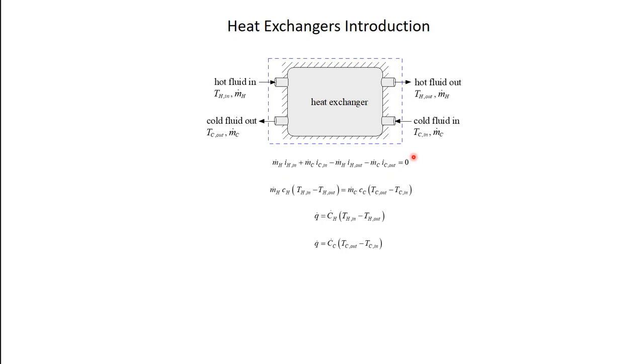If I want to go from this equation to the next equation, which is the one we typically use, I'm making another couple of assumptions, basically related to how enthalpy is behaving. I'm assuming that enthalpy can be written as specific heat capacity times temperature. So that actually does a bunch of things. It says that I'm ignoring any pressure-driven enthalpy changes, right? Enthalpy actually is a function of pressure. I'm ignoring that as being small. And it also says that the specific heat capacity is constant, right? Those are assumptions that should be checked, and they're not always very good assumptions, right? But if you can make those assumptions, then this is the equation you have.